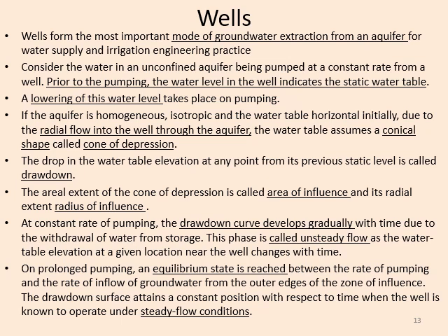The drawdown surface attains a constant position in this equilibrium state, means the water will not go further down in the well with respect to time, and the well is known to operate under steady flow condition.